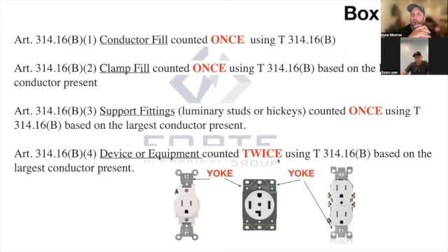So when you're pulling wire or you've got a smaller box, you need to be able to do your box fill, just because of the heat that gets trapped in there, and it starts messing with the amperage that's able to go through that wire. The ambient temperature. Exactly. So that's why they do that.